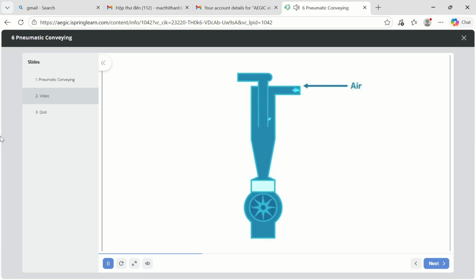The air entering a cyclone also spins, but is unable to pass out of the bottom of the cyclone, and exits upwards into the manifold. The air entering a cyclone slows, allowing solids to slow down and drop under the influence of gravity. Eventually, the solids exit through a rotary seal.